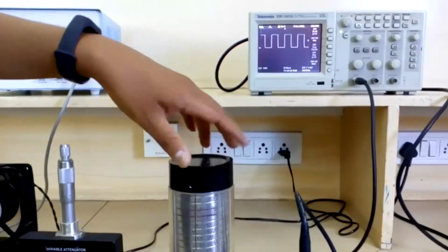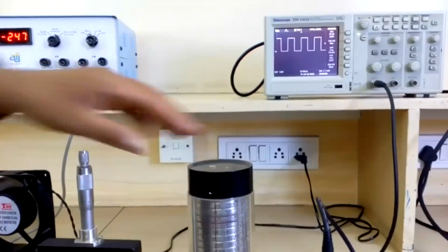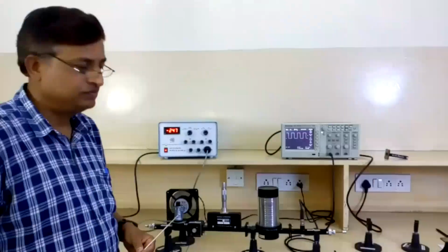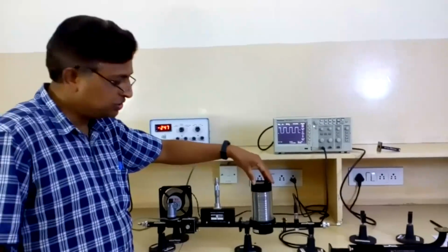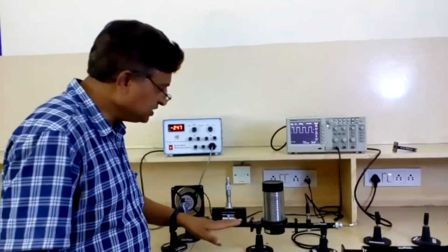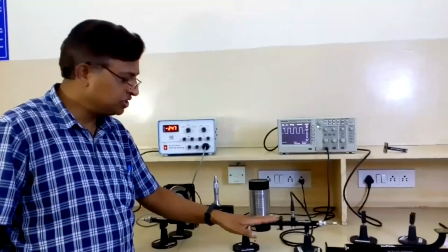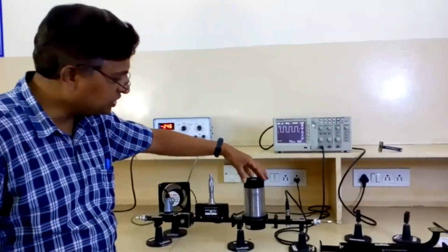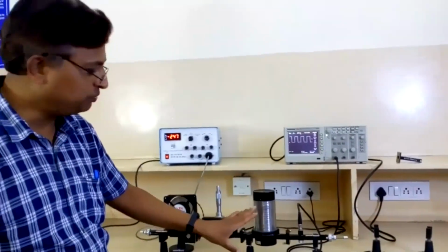As it is not tuned now, while measuring the frequency, we can understand the frequency meter can be used to measure the frequency inside the waveguide. If at all a student wants to measure the frequency which we are saying in the X band, that can be measured using this frequency meter. It works on the cavity resonator principle.